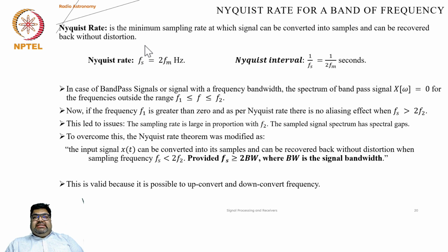However, we are discretizing, meaning we are missing some timestamps in the signal, but we have to ensure that the loss of those timestamps does not cause any loss of information in the final signal. And if we do the sampling at a particular rate or above it, then we can recover the signal without any loss of information. That's what the Shannon-Nyquist sampling theorem is all about.